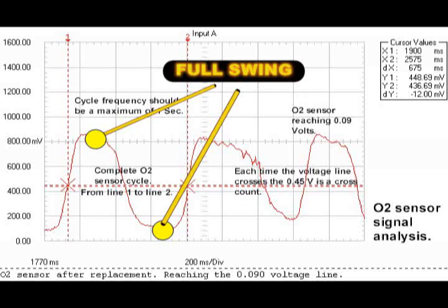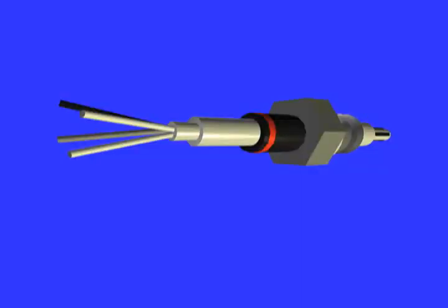Leave the engine to idle for 3 minutes, then goose the throttle again. If the O2 sensor changes from 0.1 to 0.8 volts, then do a frequency test. Raise RPM to 2500 and make sure that the O2 sensor changes at least once per second. If so, then the O2 sensor is fine. If the previous test passed but the O2 does not change at 2500 RPM, then you have a mixture problem. Do not replace the O2 sensor if it passes the swing test.